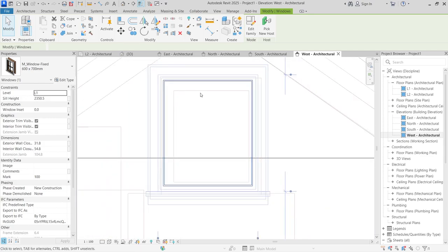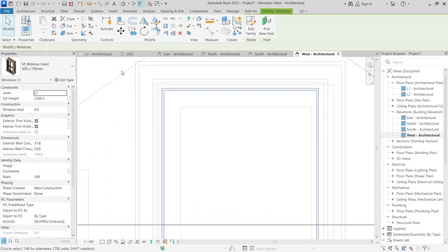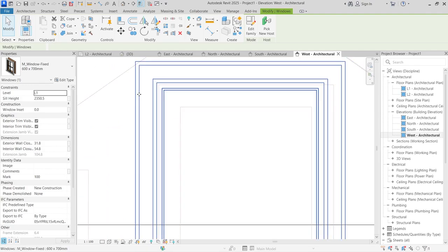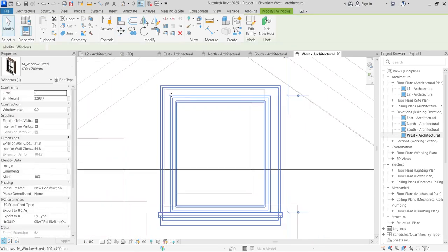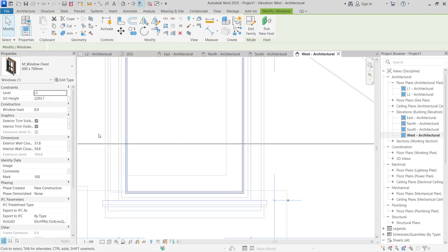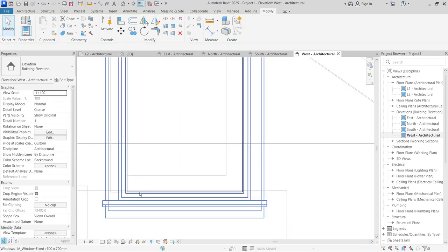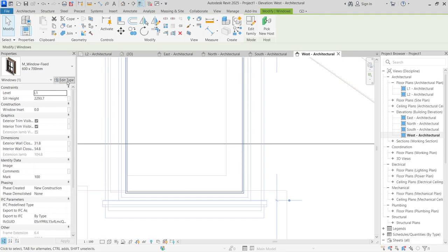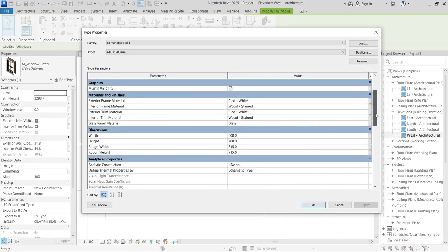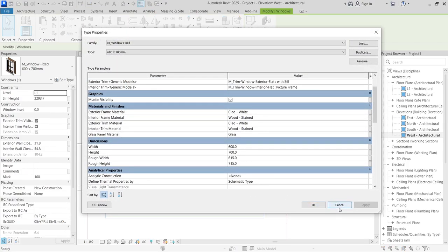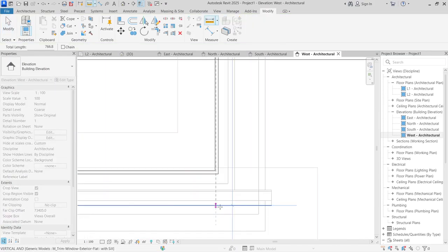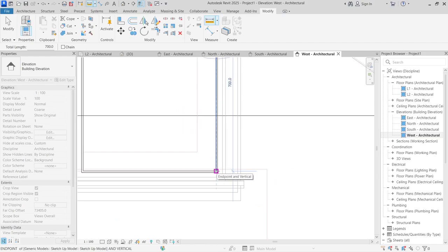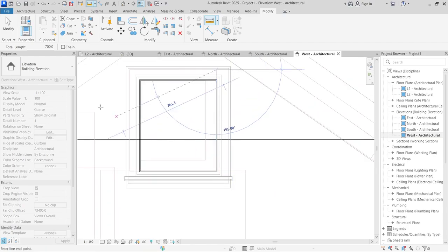We have to align this window properly with this one. So I think it's the internal side of the window. So let's try using the internal side of the window to the internal side of this one. This is me trying to be perfect, so I'm going to check this window again and be sure that the dimension of this window is actually how we want it to be. It says here 600 by 700, so let me use a measuring tool to measure the SketchUp window. It's 600 by 700 on the outside.